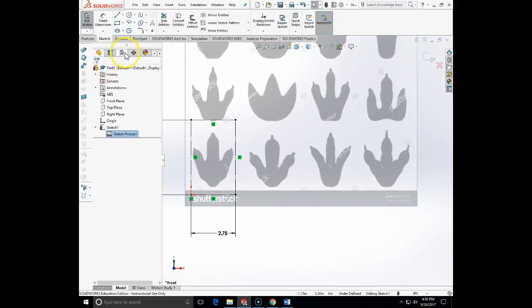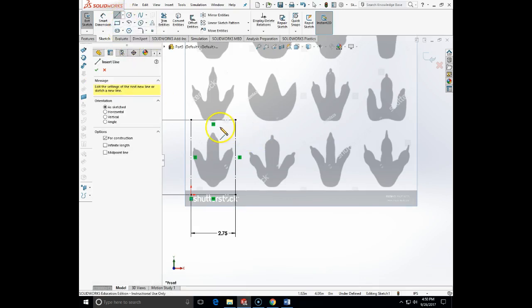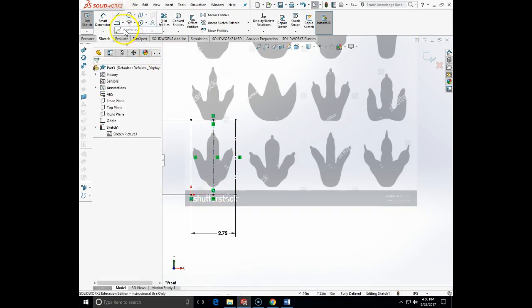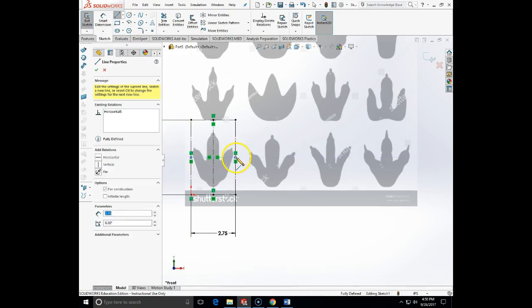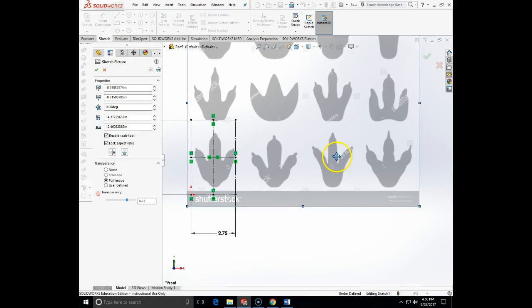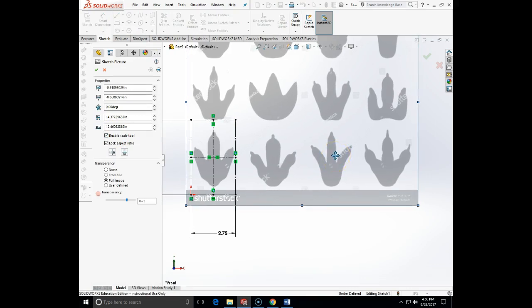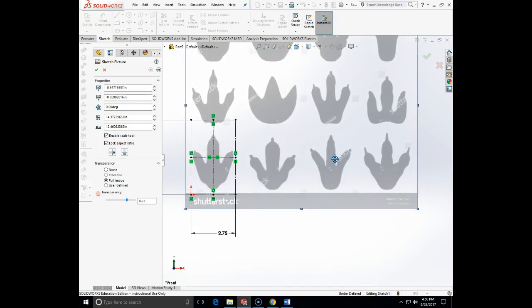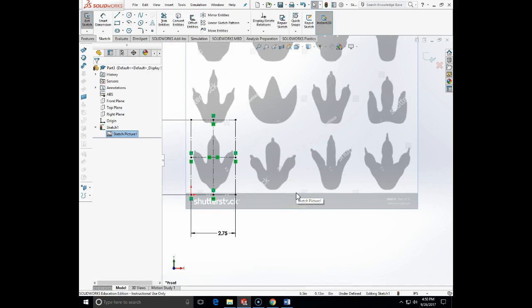I'm going to make a vertical center line so that I'm able to center it, and a horizontal center line to set the position of that picture. Here is the center. And I'm going to pull it a little bit below so that the switch is going through the middle finger of the dinosaur. Okay, so this will be my general layout for the switch plate.